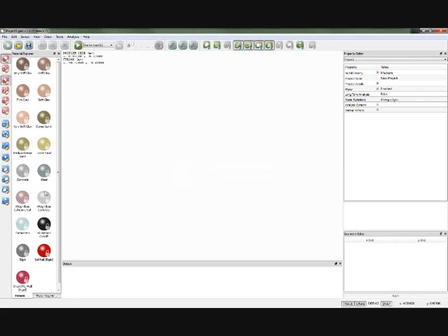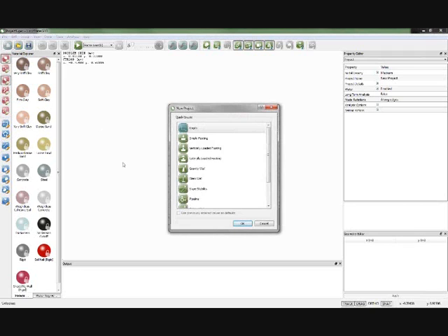To start a new project, you just click the button New, and you get a choice of projects. You can start with empty and draw your own geometry, but the software also has quick build wizards to generate standard geometries, which can be modified later. We'll use a slope stability one.